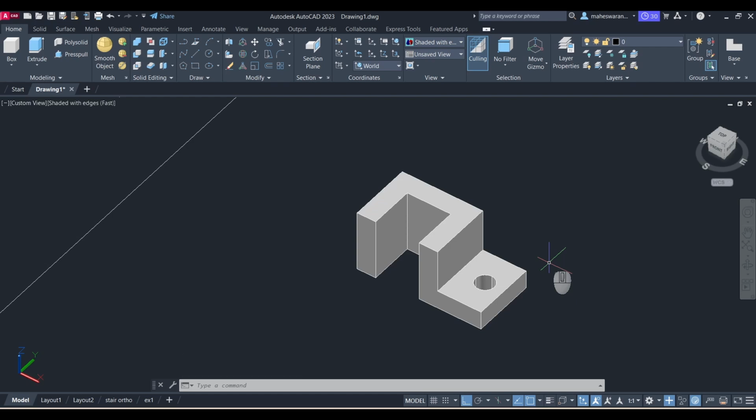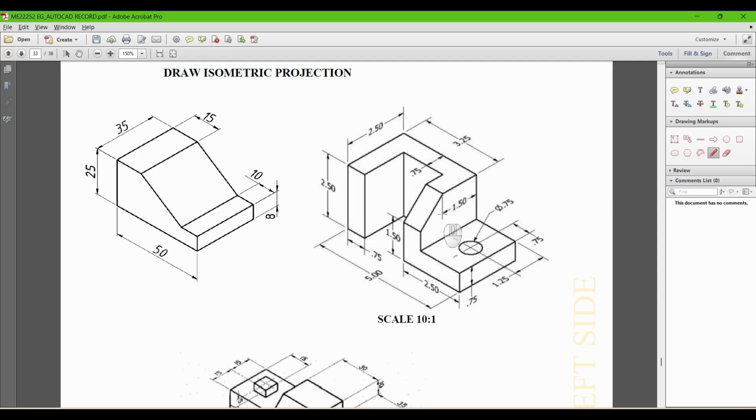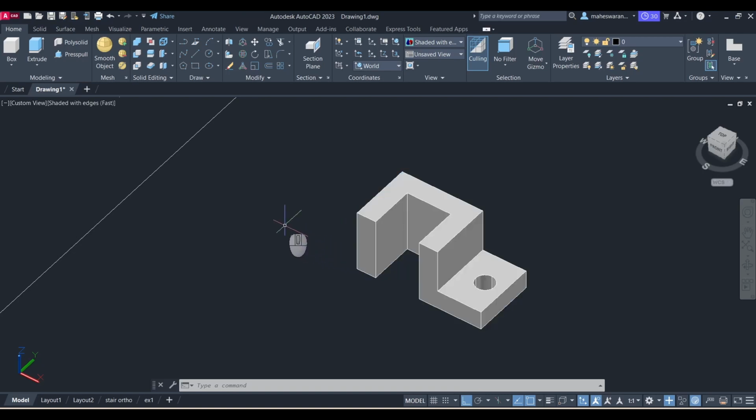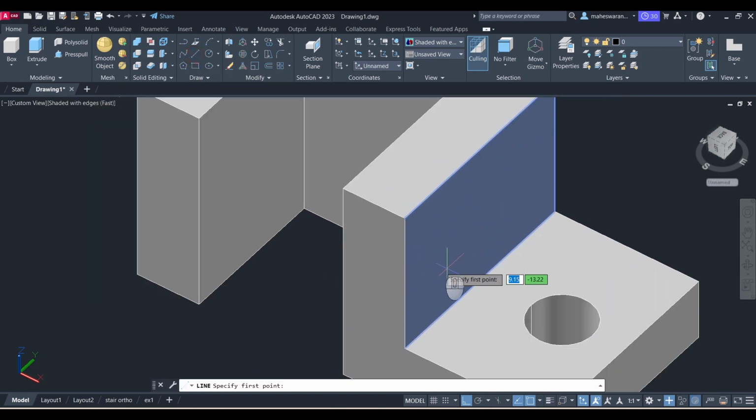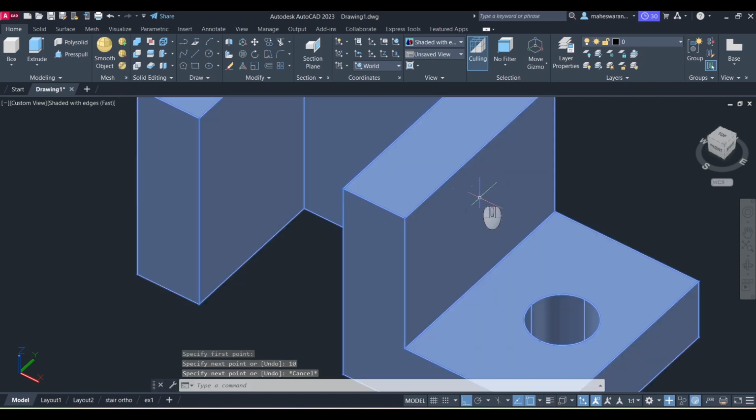Okay. The next step is I have to remove this portion. So from 1.5, okay, remaining. So totally it is 25. 15 has been removed, which means 10. Okay. So I have to draw a triangle of 10, which has to be removed. So to do that, make sure your UCS is enabled. Let me go to a line. From here, let me go here. Let me drag it. So make sure this is selected. Go to this corner. Select it. Just move 10. Enter. Next, press OK.